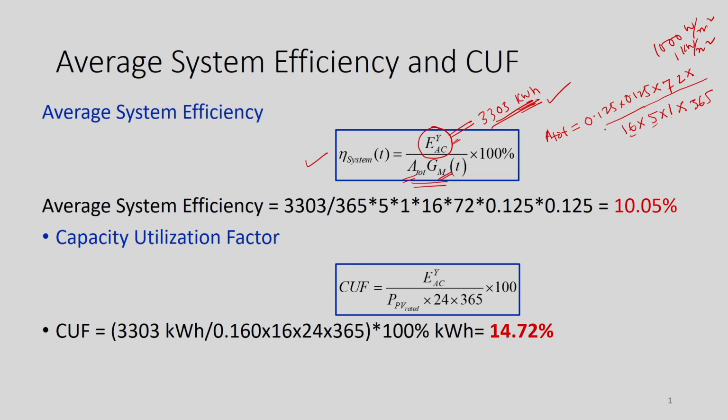So, it becomes the yearly amount of radiation received by the solar panel, right. That is how this is 365 into 5 into 1, this is 5 hours. So, the peak sun hour was 5 in this continued problem, and this 1 is 1 kilowatt per meter square, and then this part is nothing but the area of the panel.